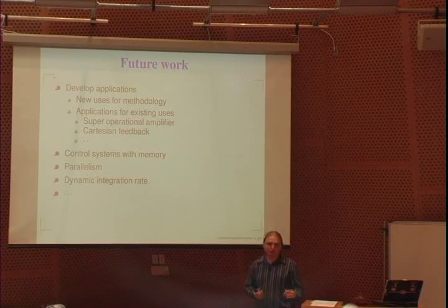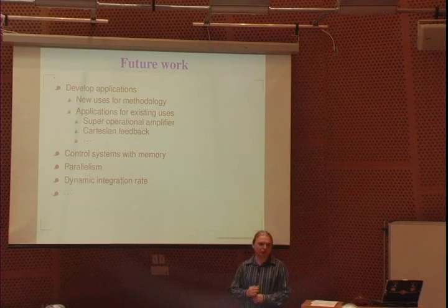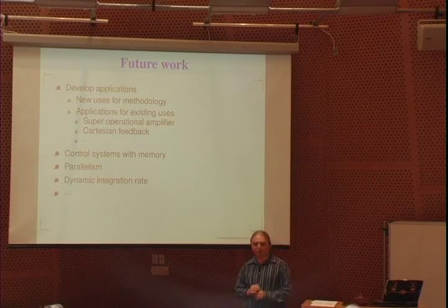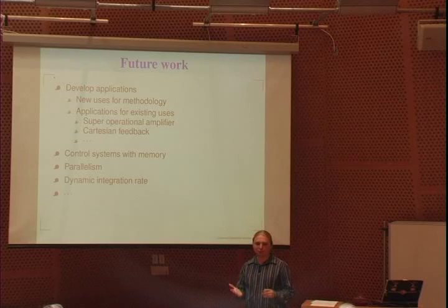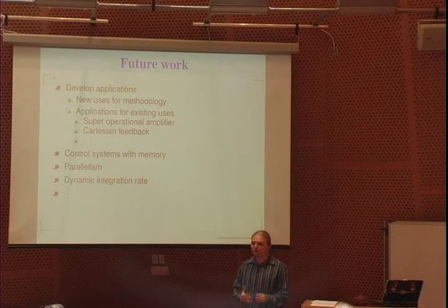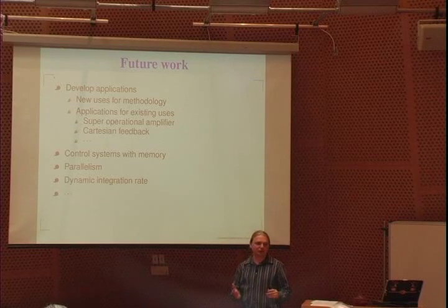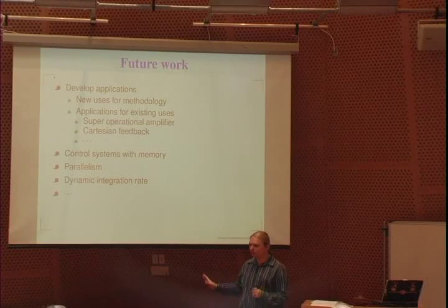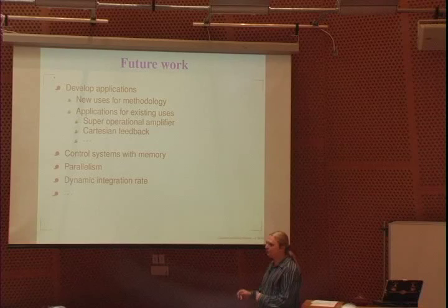And you can even think about doing things like trying to use a modeling block to model the relation between those bias currents and this distortion, and that gets to be a really hard engineering problem because you're dealing with very different time constants, and you're dealing with some problems with presenting enough signal diversity to the modeling stage.